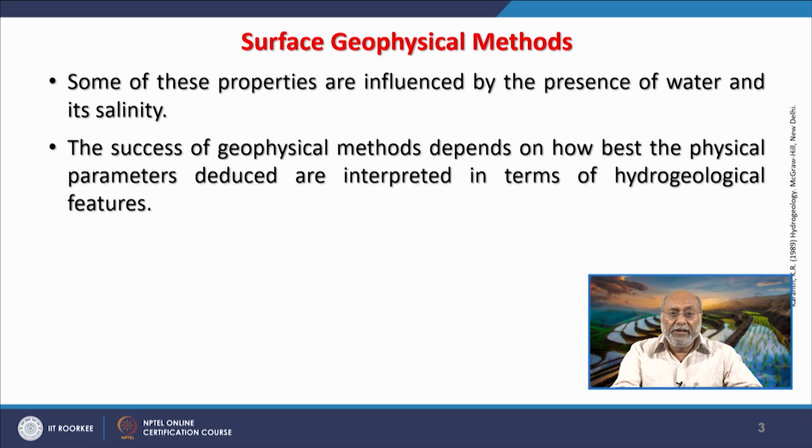What I am trying to say is that we cannot go blindly for just resistivity surveys everywhere and say that things can be done. If it is a hard rock terrain, then sometimes a resistivity survey will not yield very good information about subsurface geology. So, geological methods will always remain the first step in this direction for groundwater exploration, but they will also support deciding which geophysical method should be adopted first to deduce the hydrogeological features.